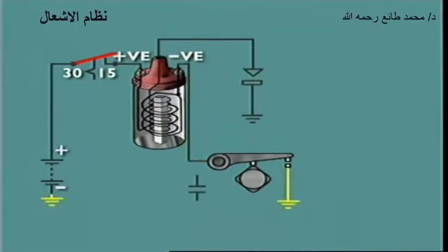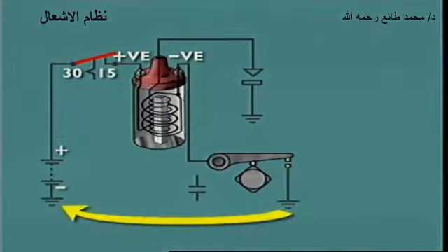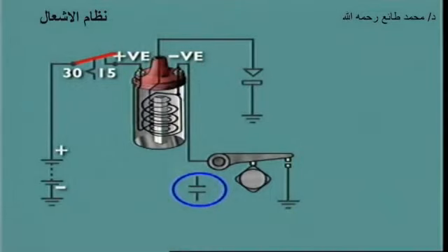The fixed contact point is connected to ground at the vehicle frame, as is the negative battery terminal. This allows the circuit to be completed through the frame when current is flowing. A capacitor is connected in parallel with the moving contact and also has a ground connection through its retaining screw.